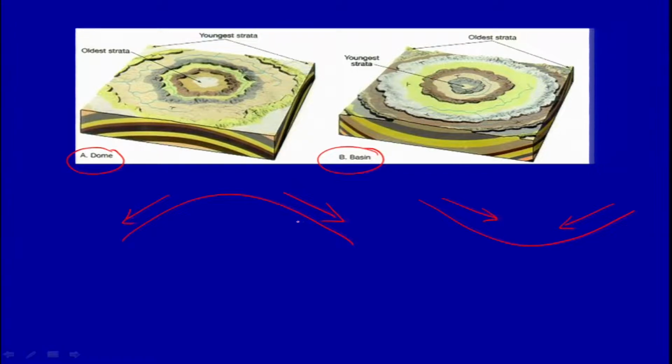So what will happen is exactly the opposite. The streams which will develop over the slope will flow away from the hinge part. So now what we have done here is that we are using drainage pattern and trying to identify the landform, but at the same time, if you have very clear information available on the satellite data, you can also pick up the dip of the beds, or the strata.